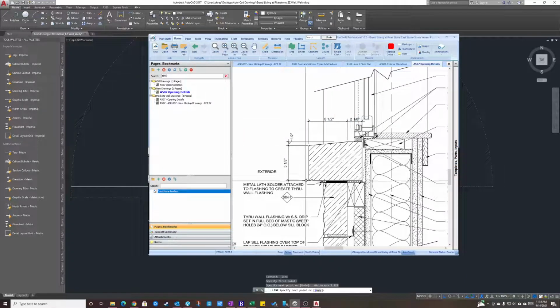It's this dimension plus that dimension. Now I drew it from here to here, so we want to draw this back dimension, so we're going to have to add these up, this dimension and this dimension. So it's 5 inches and 1/8 plus half an inch is 5 5/8. So in decimals, that's 5.625, right?